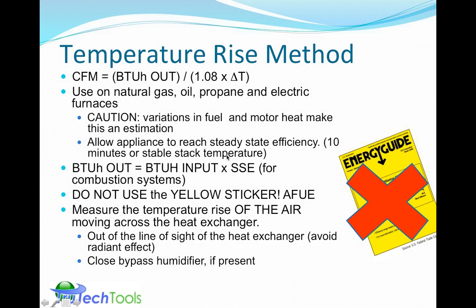And when you do this, the technique, of course, matters. In this case, you want to measure the temperature rise of just the air that's moving across the heat exchanger, because that's what's being heated up, and that's what you're looking for in this equation.